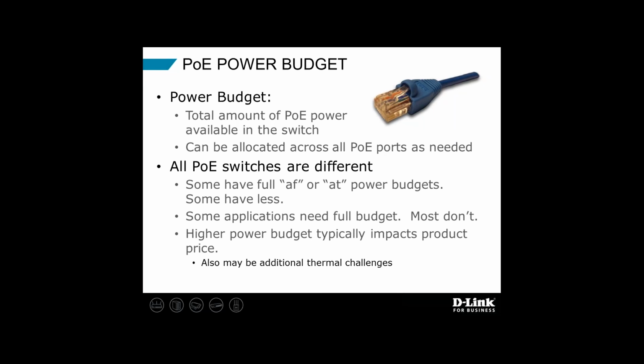Most IP cameras, for example, I'm running an 8-port switch at home, and I have 8 IP cameras, and each camera is drawing between 2 to 6 watts. So I don't really need a lot of PoE budget in my switch. On the other hand, I do recognize that there are some wireless access points that support the new standard, the AC standard, 802.11ac, and those do need a significant amount of power. And so if you've got an 8-port switch and you're powering 8 access points, you may need an 8-port switch with a higher budget.